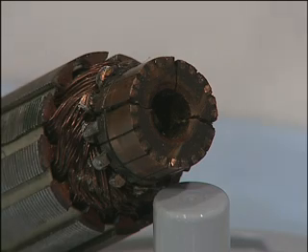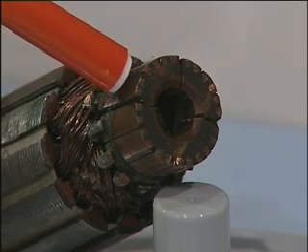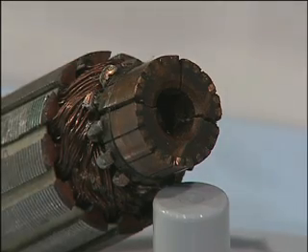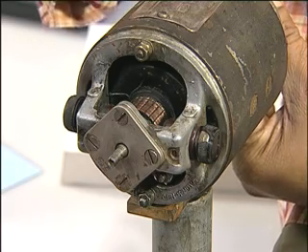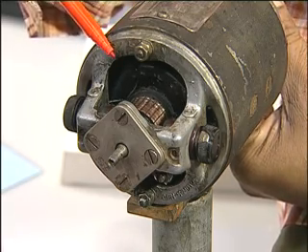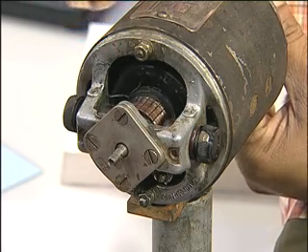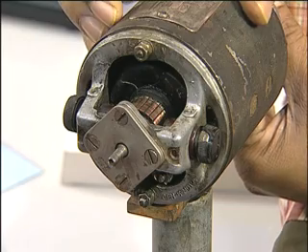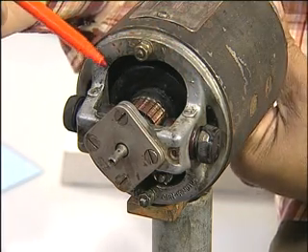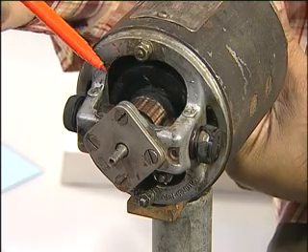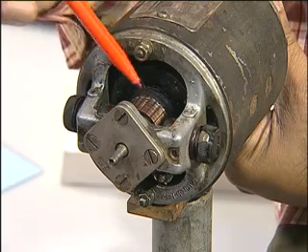So, the brushes will come in contact like that. It will be spring loaded. We will have a look at that in a different machine. You see that this is the armature which is fully mounted onto a yoke, and this is a complete motor which you see here. The shaft is capable of rotating here. So, when the shaft rotates, the commutator segments here, which are the coppery portions, make contact with the brushes.